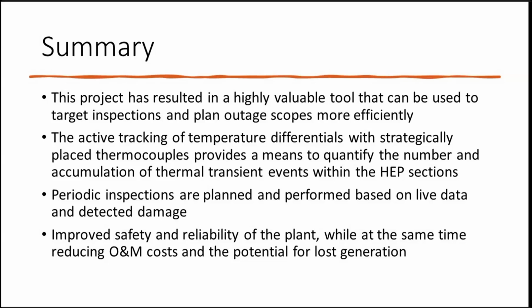Gotcha. Eugene, I'd like to waste 2 minutes and ask you another question about that. Was the pressure control valve also opening, or was just the spray valve opening on that? It was both. The hot reheat bypass pressure control valve would pop open randomly during these low load conditions, and we were seeing very high differentials. Kane could probably correct me, but over 400 degrees on some of these events, and very large differentials, very damaging. And then, of course, you've got your spray valve that opens in conjunction with the pressure control valve. Okay, great. All right, thanks.